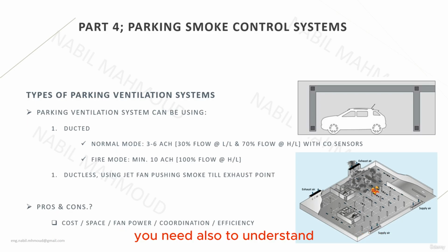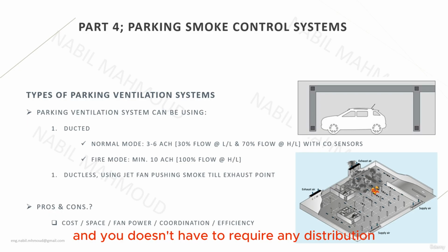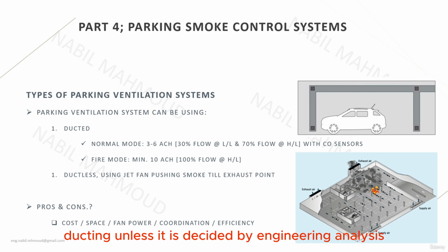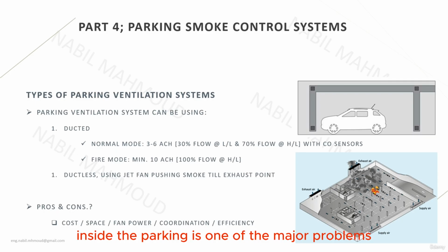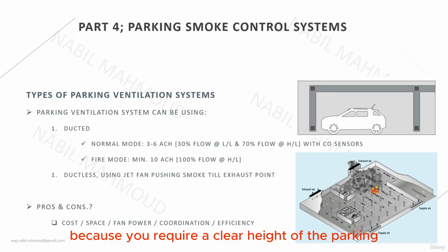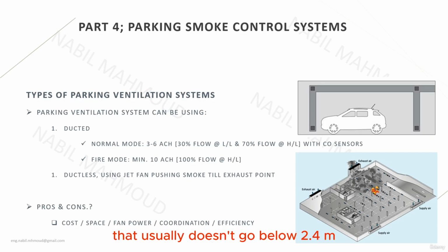You need also to understand that jet fans do not consume a lot of power and do not require a lot of space. Actually, the diameter of the fan is very small, and you don't require any distribution ducting unless it is decided by engineering analysis. So from a space point of view, the jet fan will win this comparison because ducting requires a lot of space. And of course, the vertical space inside the parking is one of the major problems because you require a clear height of the parking that usually doesn't go below 2.4 meters.